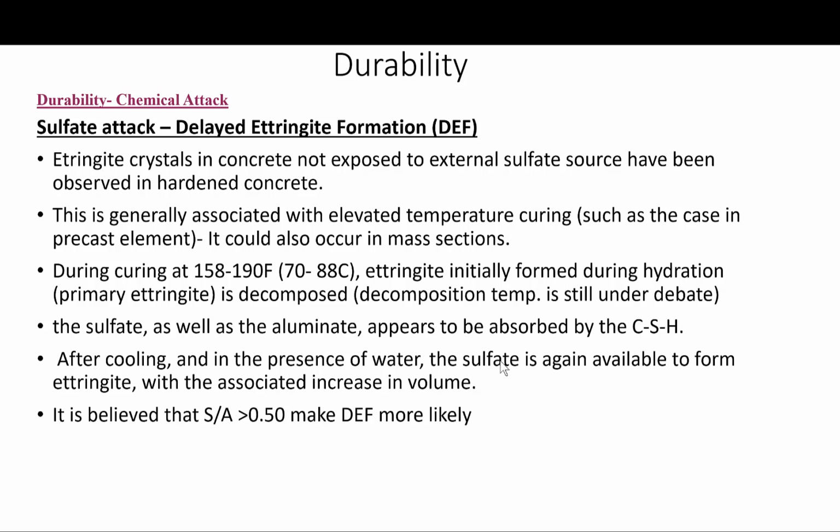For concrete exposed to significant moisture, the specific mechanism of DEF is not fully understood. But again, as reported in the literature, it does appear that incipient damage from other causes such as alkali silica reaction or thermal gradients is a necessary component for the Delayed Ettringite Formation to cause any deleterious expansions.